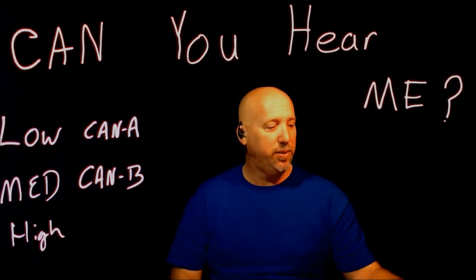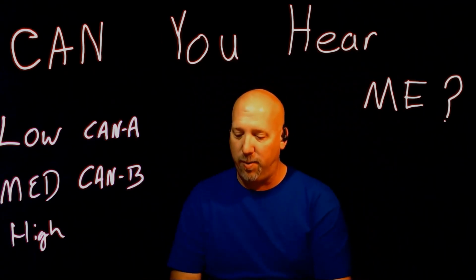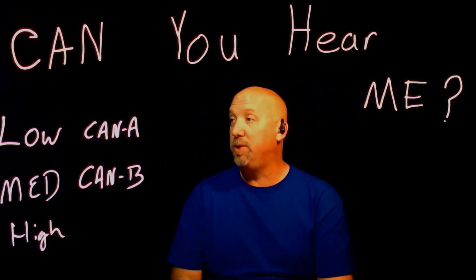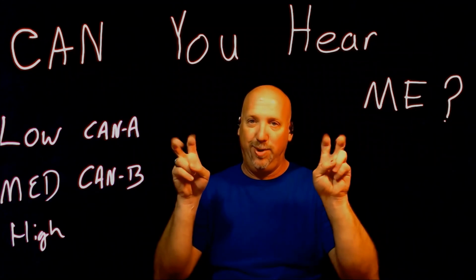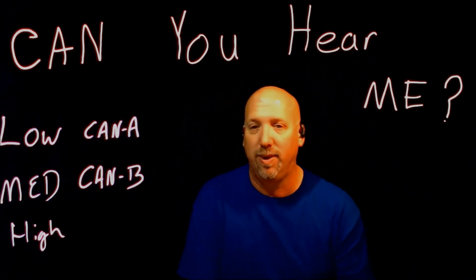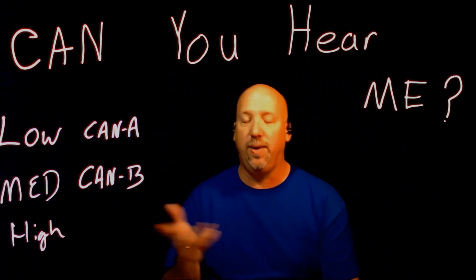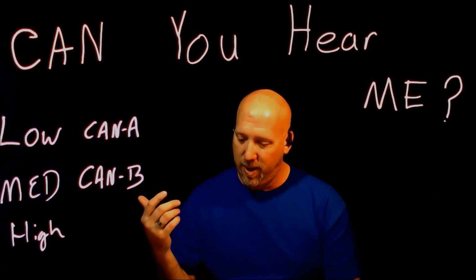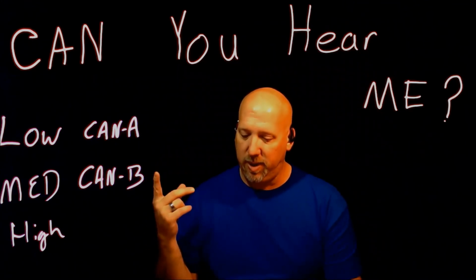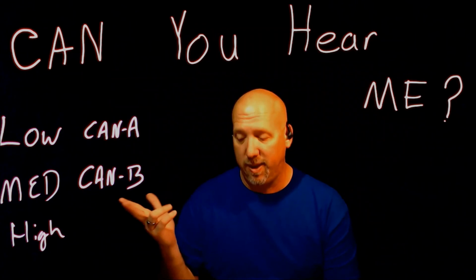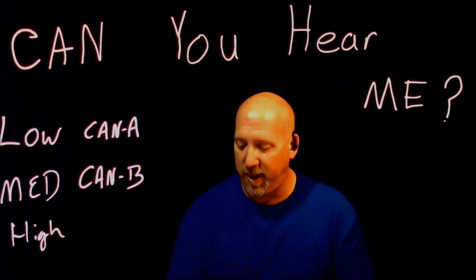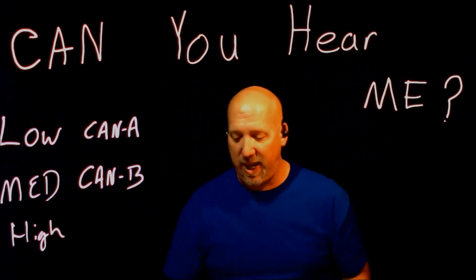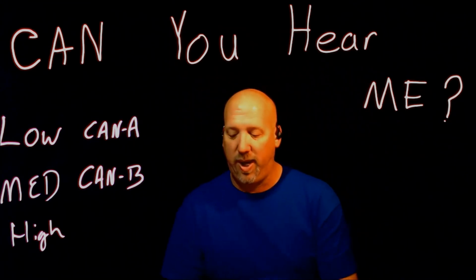It can be a single or a dual wire network, depending on what each manufacturer calls medium speed. It just depends on the manufacturer that's using the medium speed, in quotation fingers, because it's really up to the manufacturer. There are exceptions here. GM's use of medium speed GM-LAN circuit is at DLC pin 1. That's the one that will actually be at the DLC. And Ford's use of the MSCAN is at DLC pins 3 and 11.